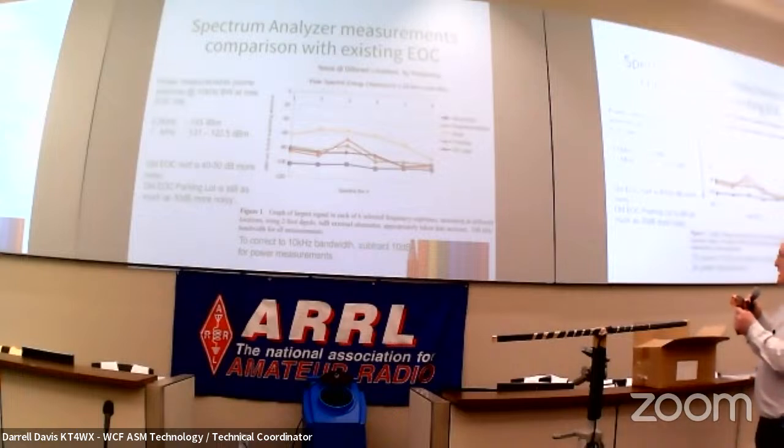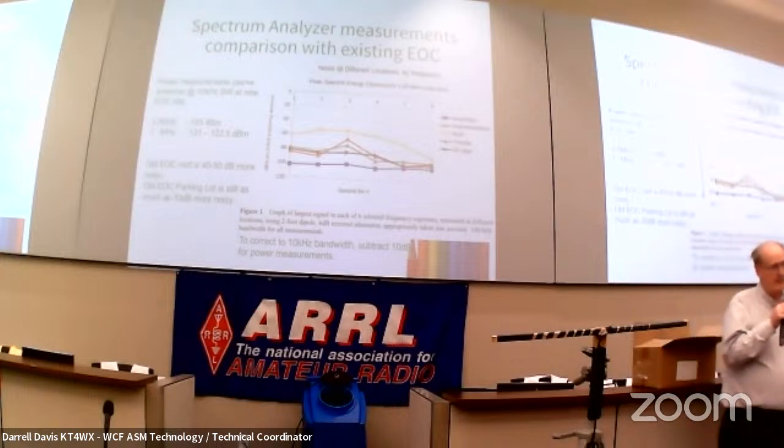Now, this was data that we did. This is the noise floor back when I made that measurement. I didn't have it set up quite as well as I did this time. And these were measurements that were done in the parking lot and on the back corner of the building. And what we discovered was the noise that our building generated was near field noise.